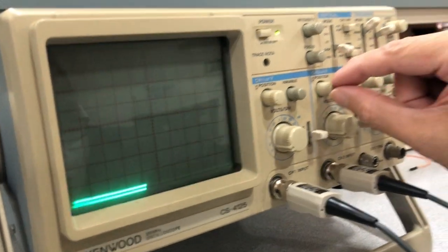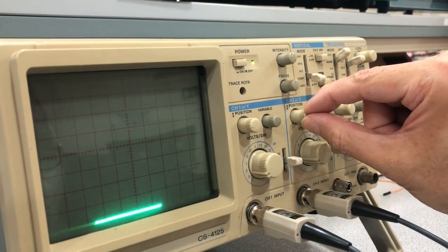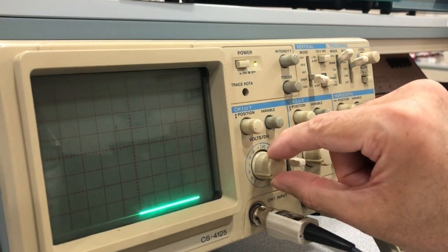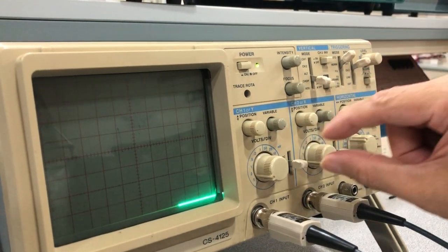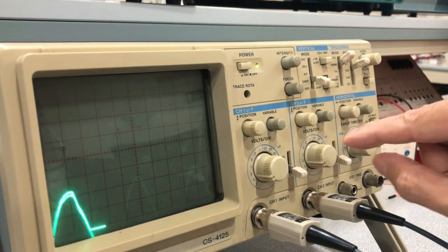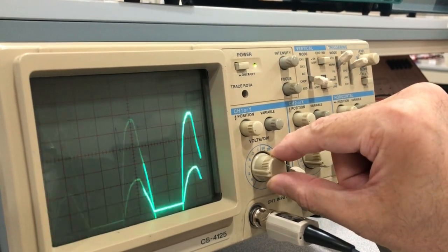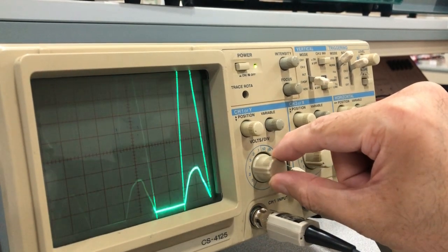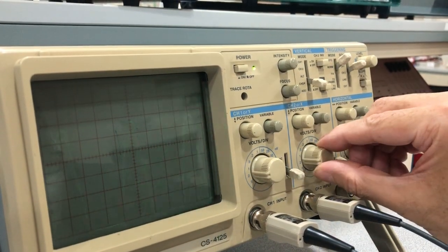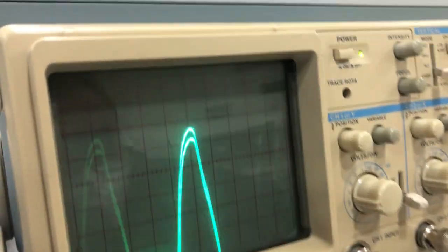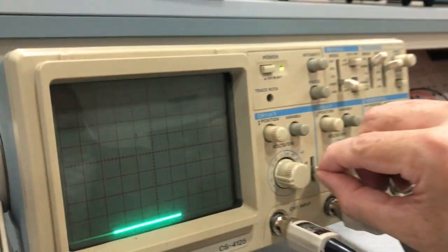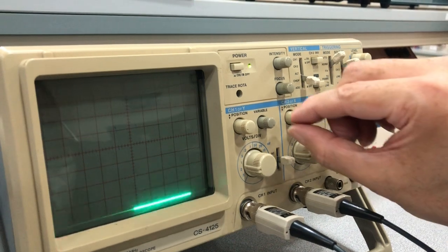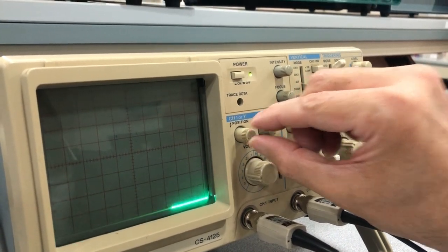Okay. Now, very sensitive. Now I go to DC, but I increase, I should have centered, I increase to 2 volt per division, 1 volt per division off the screen, and this is 2 volt per division. Okay, but let me double check my horizontal is still centered around the bottom horizontal line.